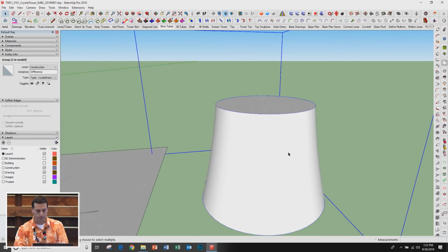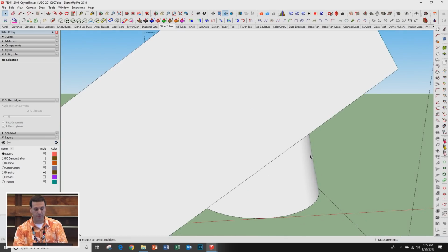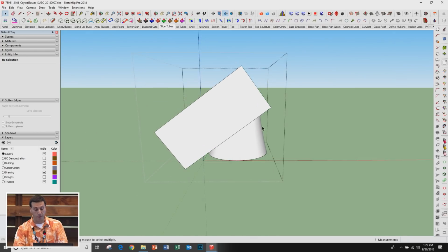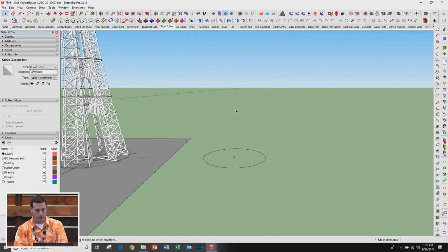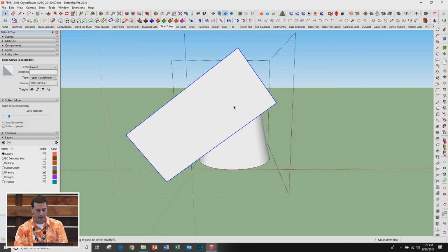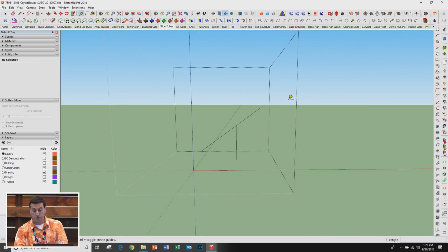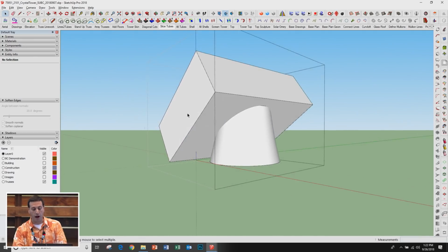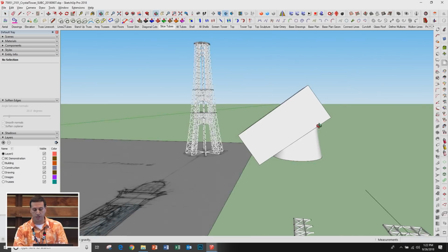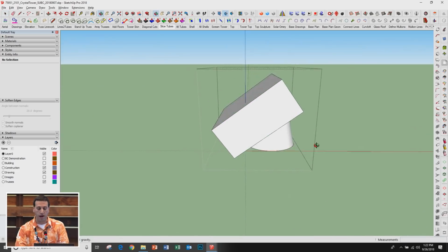And now, it was pretty easy. Let me unhide this thing. So then I drew a box at that angle because I had that line. If I hide this for a second, oh, no, it's inside of there. If I hide this, I actually had that line, which I had pulled over from my elevation. And so I was able to draw this box on that plane. And then I just sliced that bad boy off, right?